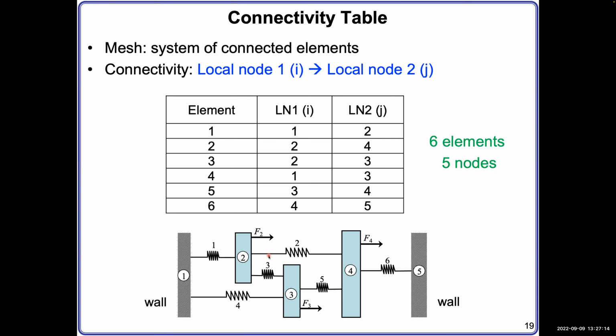But the force is not shared. Here you have a force around spring 1, a force around spring 2, and a force around spring 3. They added together will be in equilibrium with the externally applied force F2. Force is not shared. Displacement is shared. Do you guys follow me? Yeah. Okay, very good.